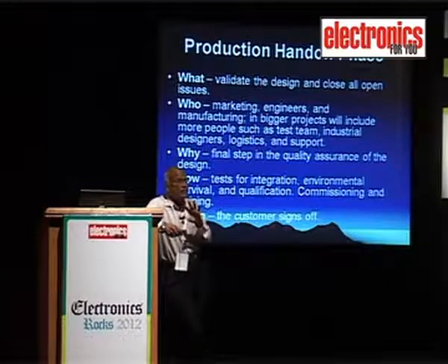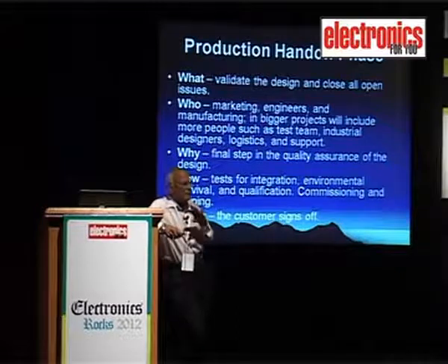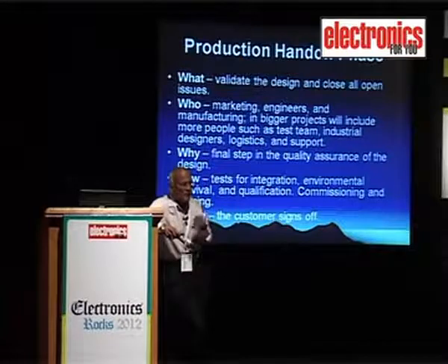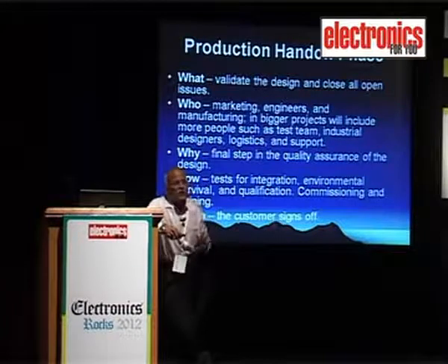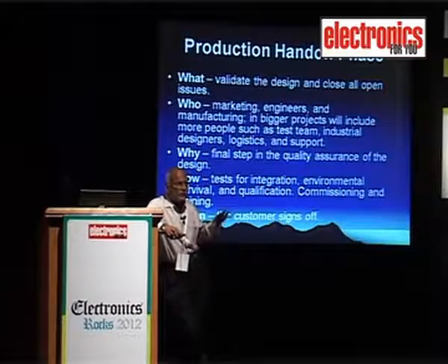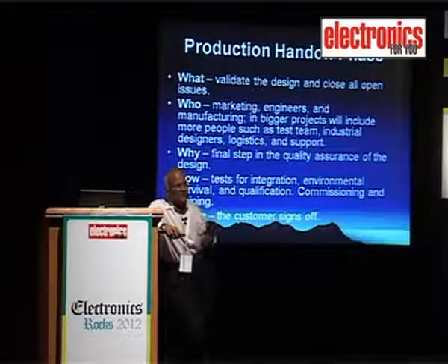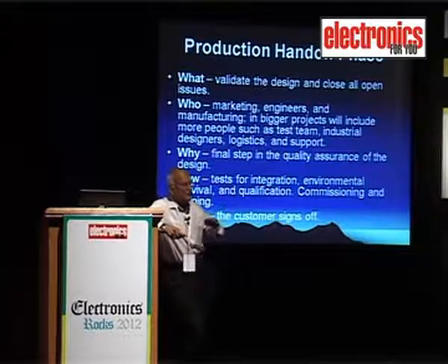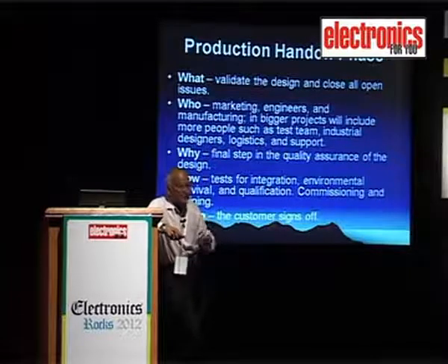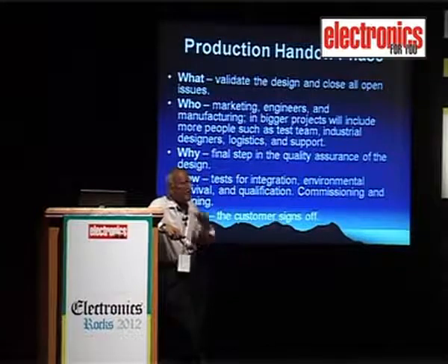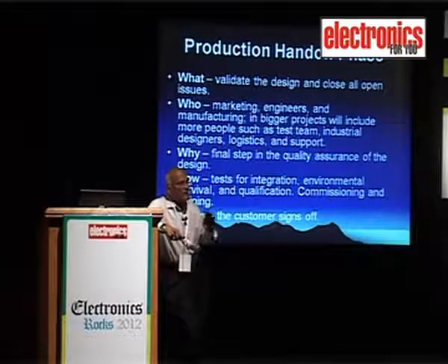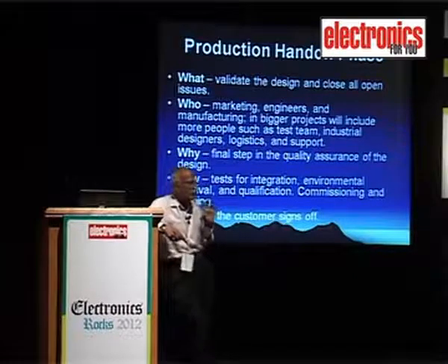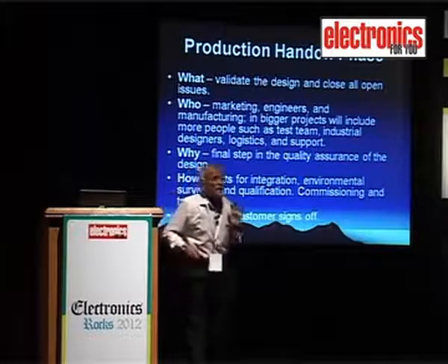The manufacturing tolerances are fairly large. Even normal capacitors have manufacturing tolerances of plus or minus 10%. When you say 1 microfarad, it is 0.9 microfarad or 1.1 microfarad. When you use electrolytic capacitors which are formed, and you made a product and it has not been used for nearly 1 year, 1.5 years, and is subsequently used, the capacitor is no longer an electrolytic capacitor. It is just a box. It may be 1 microfarad, 2 microfarad, 3 microfarad, not 100 microfarad.